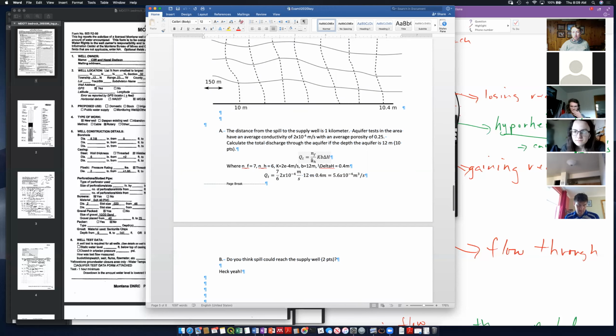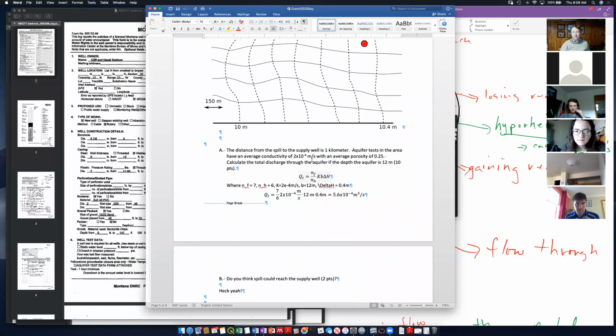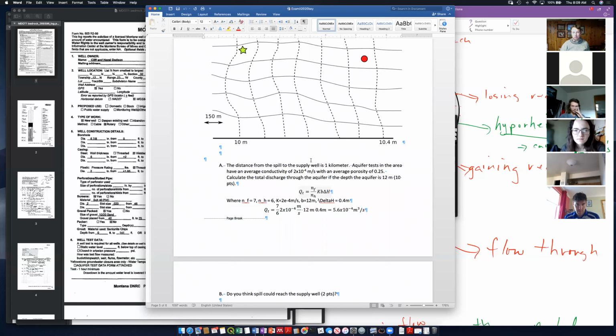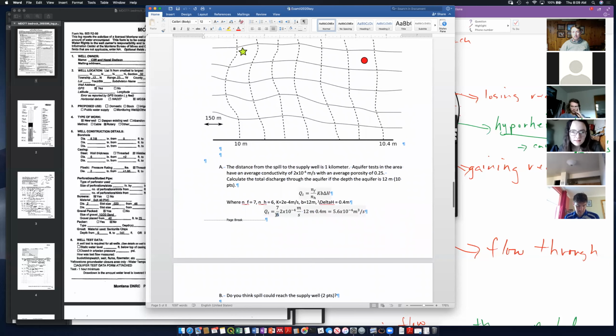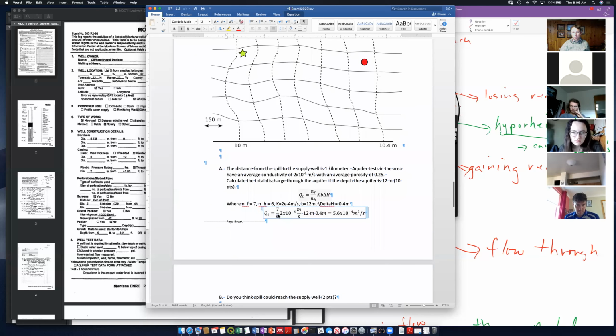And one of the things I wanted to do is to talk about how we calculate the head contours or the number of head drops, because almost no one counted the number of head drops right. So here's the point. My first head drop, this guy right here, we start at 0. So this is 0, 1, 2, 3, 4, 5, 6 head drops.